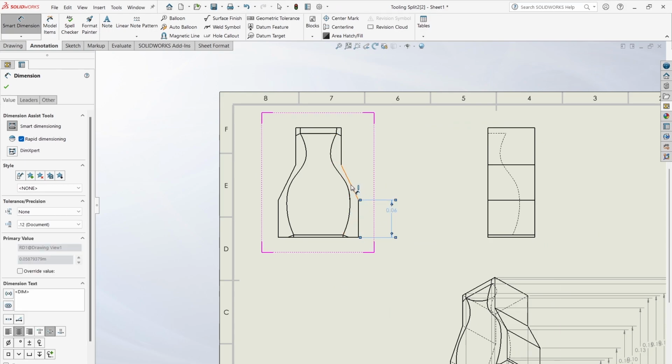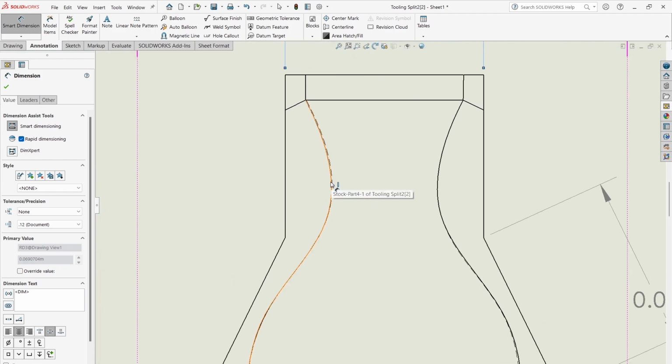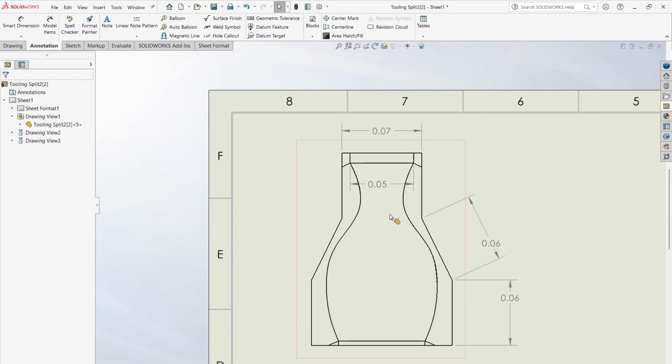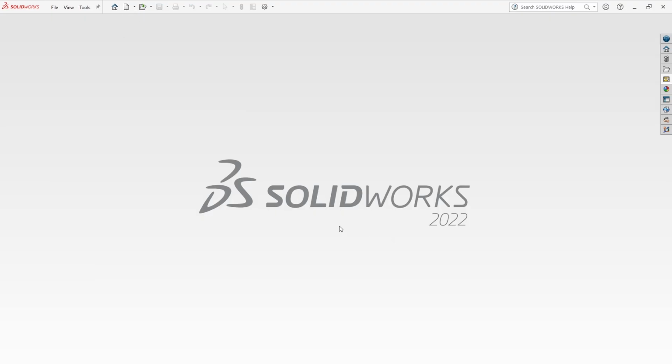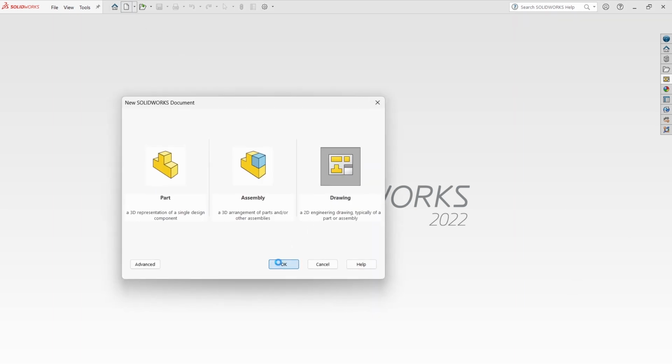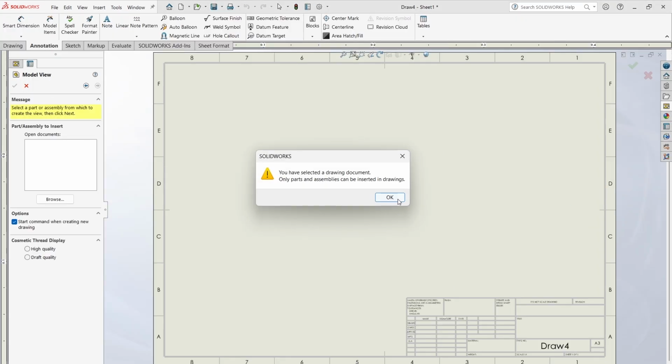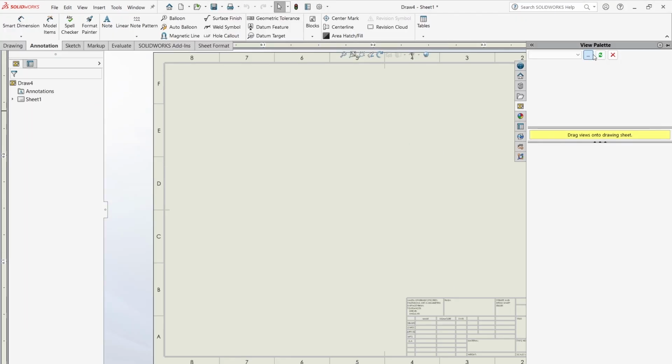This part, these dimensions. Because we made a parting line, I cannot select this dimension directly from here. Because while selecting, first we made a parting line, right? That's why I'm able to select this. So now I will save. Okay, so we are done with the drawings. I will take one last drawing, and I will also show you how to convert it into PDF format.